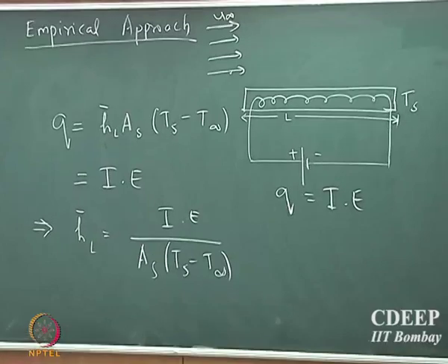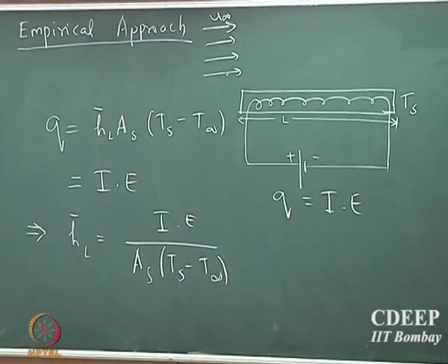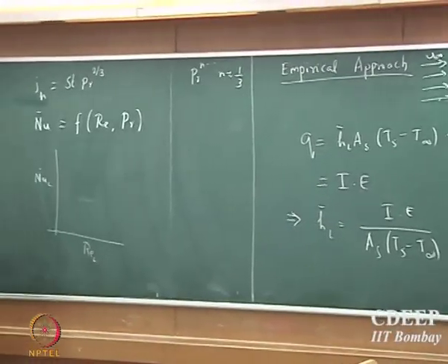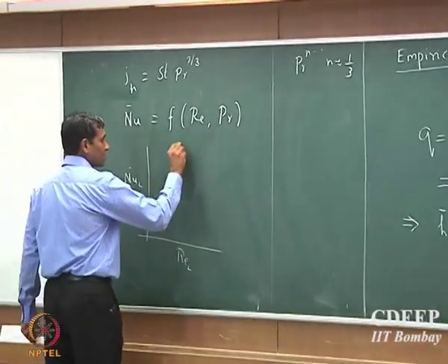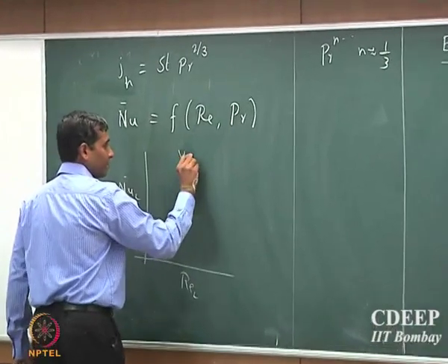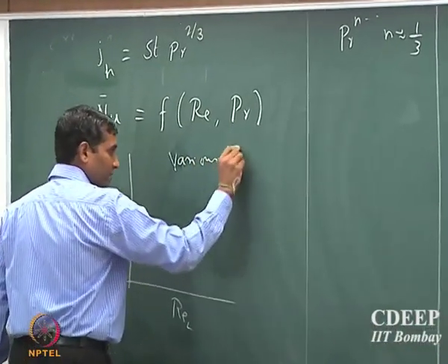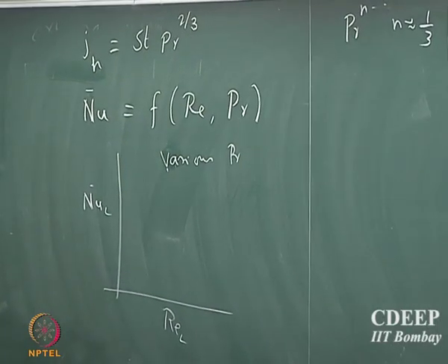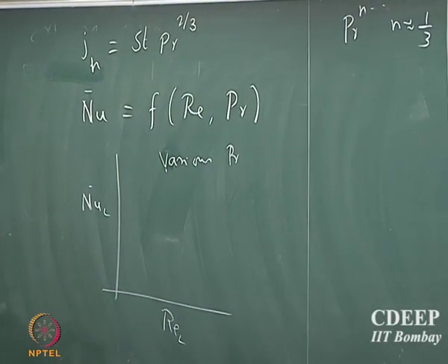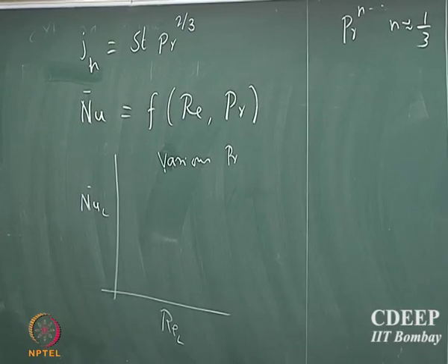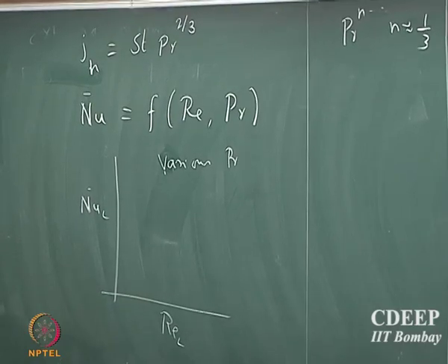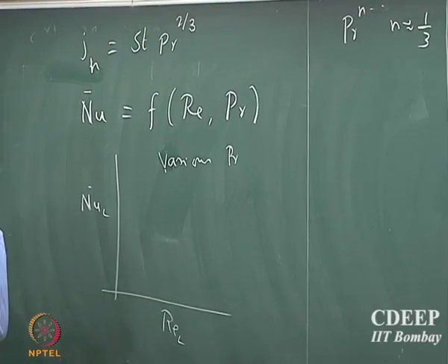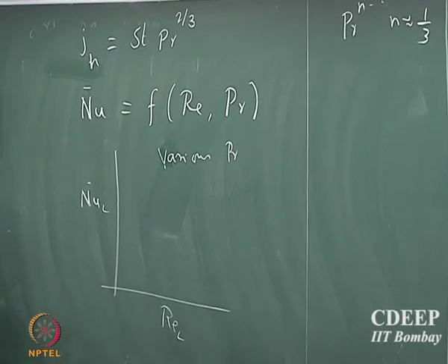is they would have first made a plot of Nusselt number versus Reynolds number, okay, at various Prandtl number values. So, note that Prandtl number is the property of the fluid. So, if you can change the fluid, you conduct the experiments with different fluids or different temperatures, where you are now able to control the thermal diffusivity and the momentum diffusivity of the fluid.